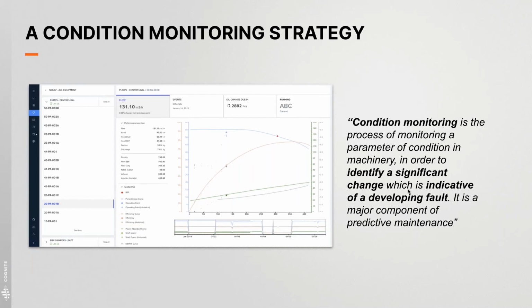On the other hand, if the technician is collecting the data from inspection, then one can automate that analysis and increase the inspection interval failure data systematically to find the optimized interval. In this case, the change in interval is written back from the optimization application to CMMS so that the work order creation is updated. In addition, data can also be collected from the control system automatically to further improve maintenance and reliability.